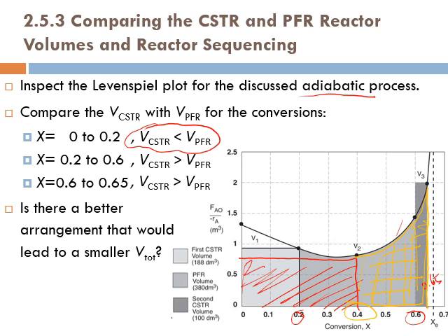But one would say, how do I make sure that my CSTR will take me to 0.4 and then my plug flow reactor will take me to 0.65? How do you make sure? Well, it's not trial and error, it's not magic. You design it. So for the CSTR, you know that the design equation is this times x1.